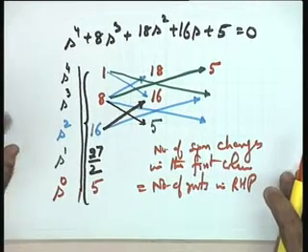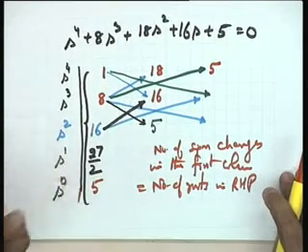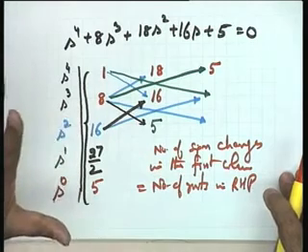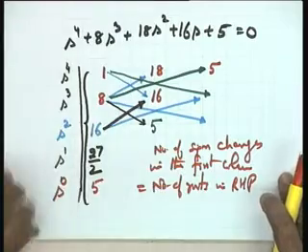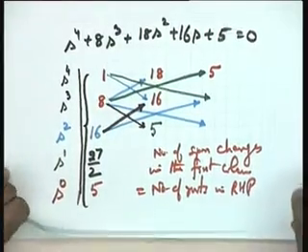However, please note it does not give you the location of the unstable roots, while the numerical analysis will give you the location. It simply tells you that so many roots are in the right half plane, the location cannot be determined using this particular criterion.